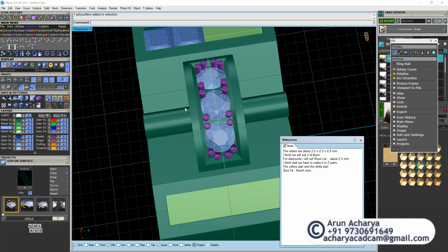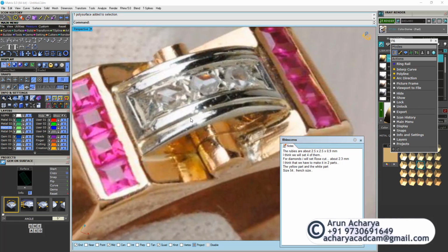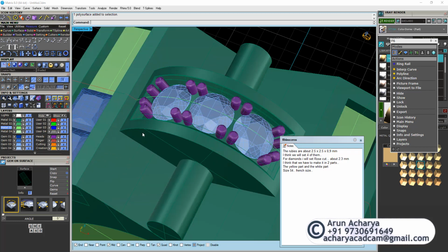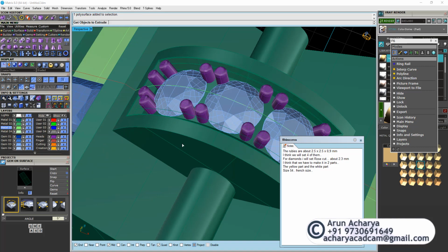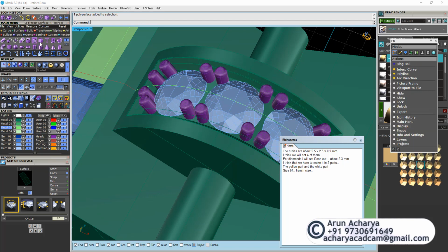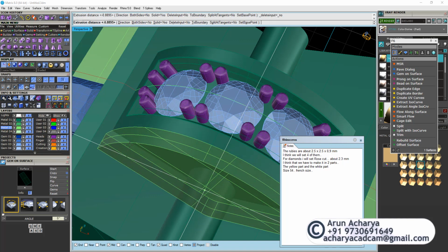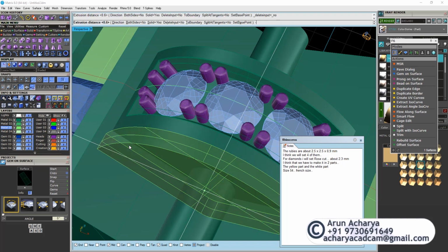And by the way, I didn't see this one. There is a double object on the side over here, so we have to extrude this again by 0.6, I would say. So extract a surface and extrude straight around 0.6, but on the other side minus 0.6.